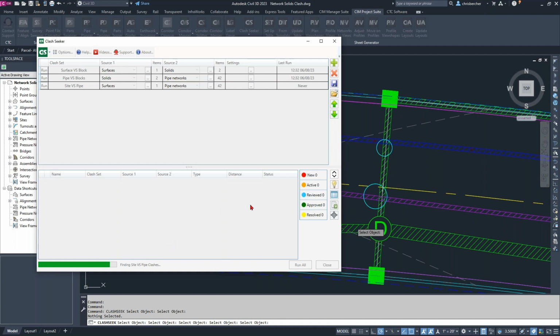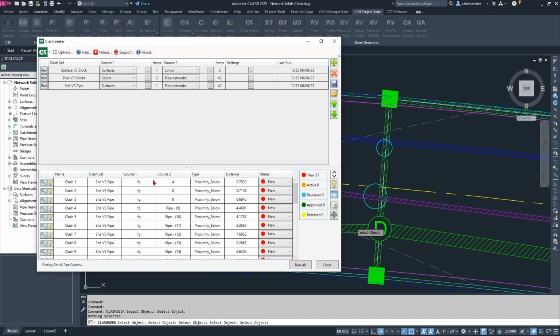All right, we're almost done here, and we'll make sure that everything looks good. Aha! So we do have a number of things here, and it tells me exactly where we've got problems, right? So I put in a 10-foot buffer, and every single one of those elements falls within that range. So according to my rule set, the whole drawing's wrong. So I would have to go back and make some adjustments, or put the right numbers in if that's the case.